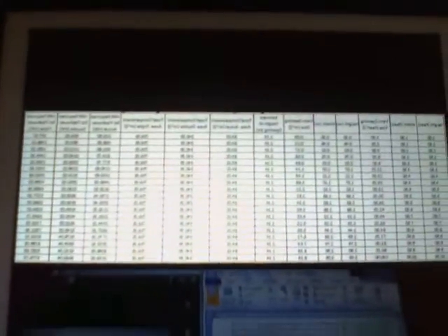Well, at any rate, that's the table. What I did was I took the ventilation opening and I just started with a standard height of 1 foot and increased it by 1/2 foot all the way up to 10 feet, and did the same with the width. Multiplied those together to get the feet squared, and then I converted each of those, the height and the width, into meters, and then got a ventilation opening size in meters squared as well, which is what I ended up using. The estimated height of the opening stayed constant at